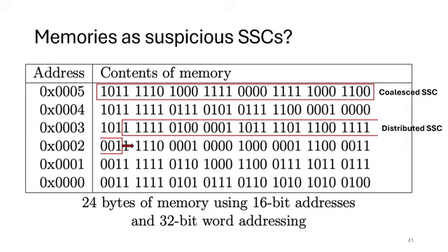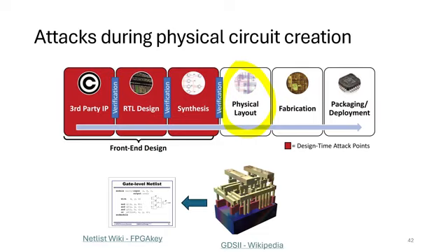Using the data flow graph, they curb the state explosion, and they create a list of these that are all connected. And so it effectively can also scan memory. You can go backwards from a physical layout that you might think is suspicious from a fabrication firm, and if they provide the IP, which includes the RTL design usually, you can reverse engineer the RTL, or just use the RTL and test it with Bomberman to see if this physical design has any ticking time bomb Trojans as well. So they mentioned that as another helpful use of Bomberman.